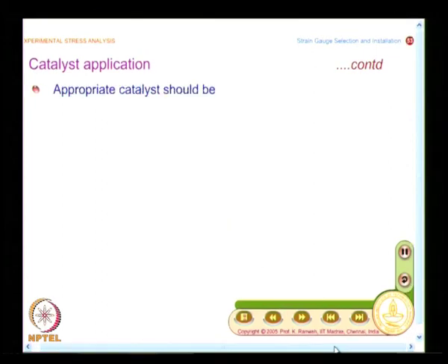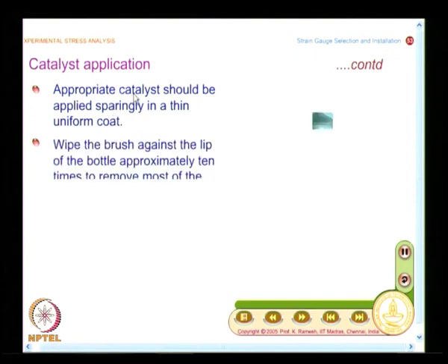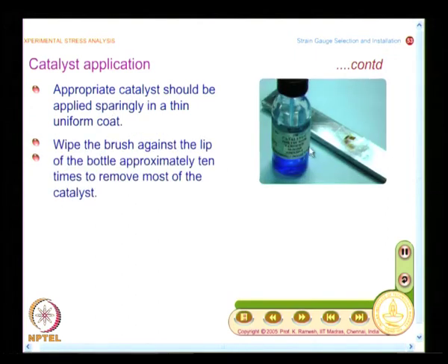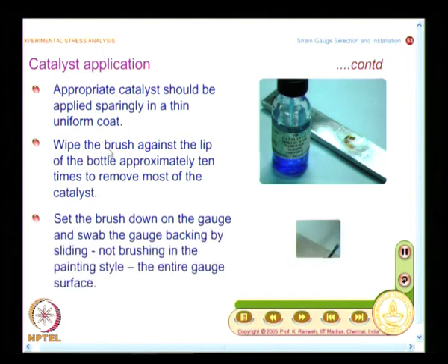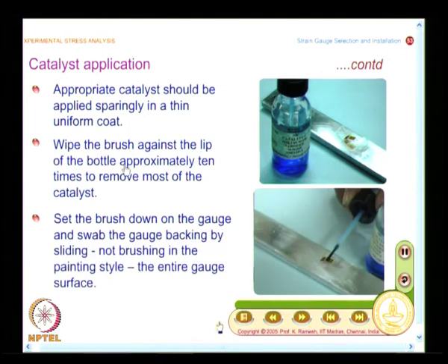And even in catalyst application, you should not apply excessive catalyst. So, the recommendation is you need to take out the brush and wipe the brush against the lip of the bottle approximately 10 times to remove most of the catalyst. These are all very detailed instructions.